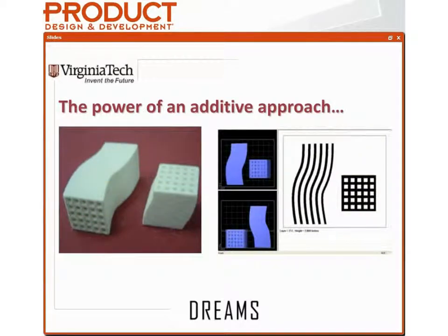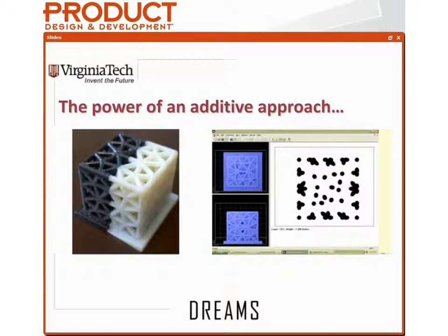Could you manufacture that with traditional technologies? Again, this is like a serpentine kind of honeycomb shape that's swept like in an S. And to our additive manufacturing process, each layer just looks like a bunch of curvy lines. If I fabricate it on its end, it's just a sort of a grid that sort of shifts left and right to make this stacked honeycomb swept approach. Now this, I would say, is impossible to manufacture traditionally. Maybe you can extrude it with a very careful pull, but there's no way to machine that or injection mold that.